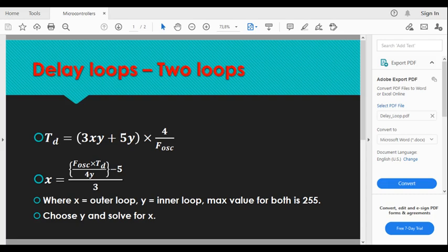It's still bigger. If you go to 150, it's still bigger, it's 265. So you go to 200, and now it's 198.33. Obviously the microcontroller does not understand floating point values, at least not in that form in assembly, so you have to take that down to 198.